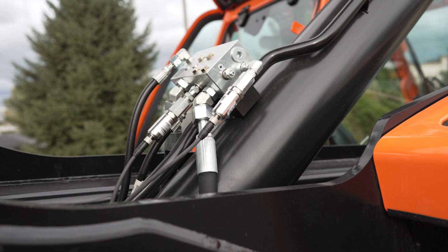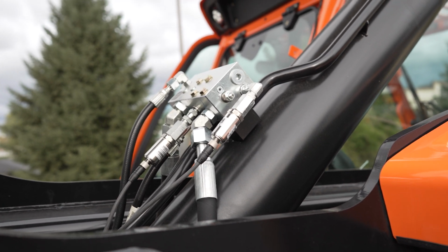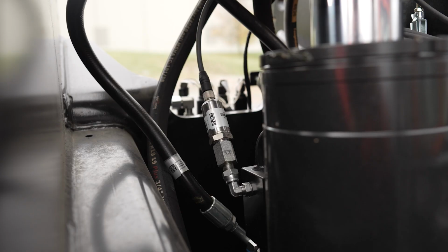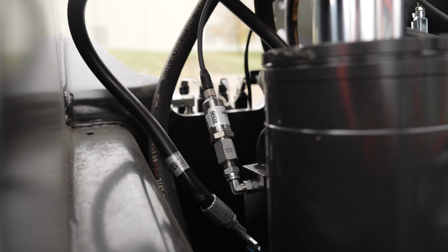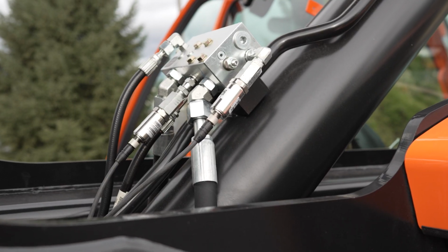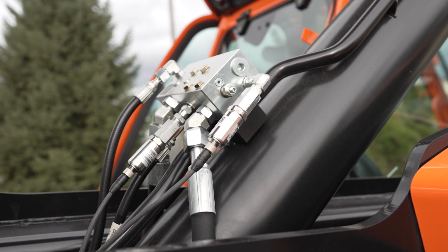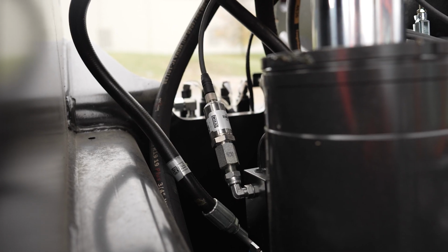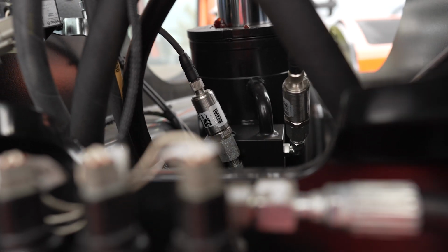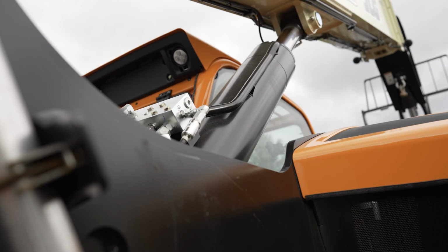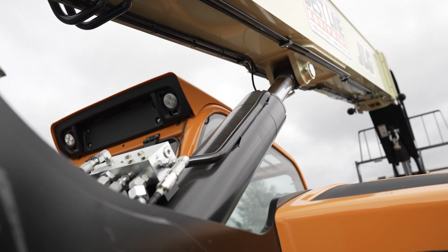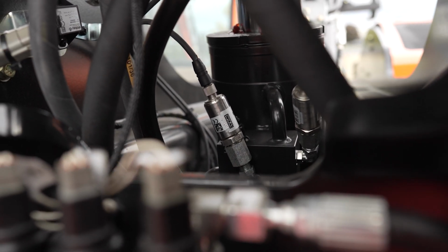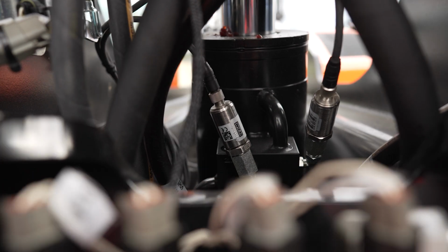A pair of pressure transducers are included for each load-bearing hydraulic cylinder. They are used to measure static and dynamic pressures of the hydraulic fluid and are connected to the CAN bus junction box. In our example, we have 2 pressure transducers on the lift cylinder and 2 on the leveling cylinder. One pressure transducer is connected to the piston side and the other to the rod side of each cylinder. Some hydraulic cylinders will include a port block and provide an accessible location to install the hydraulic lines.